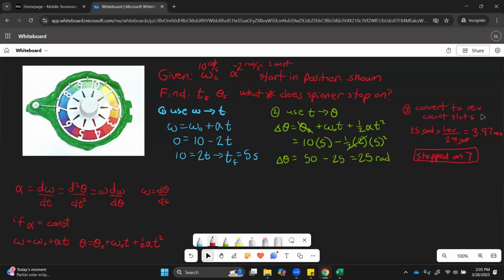So it's minus 0.1 for every number. If it was 3.8, it would have been on 5. 3.7 would have been on 4, and so on, until 3.1 would have been on 8, and 3.0 would have been on 7. So each tenth of a revolution, it's going to be on a different number.